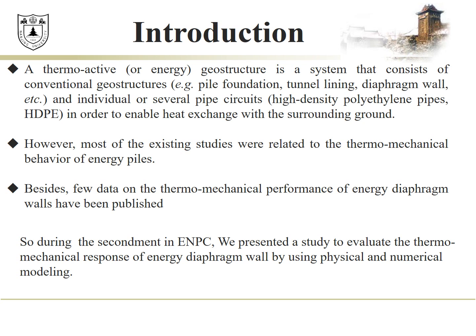However, most of the existing studies were related to the thermo-mechanical behavior of energy piles. Besides, few field data on the thermo-mechanical performance of energy diaphragm walls have been published. So, during the segment in EMPC, we presented a study to evaluate the thermo-mechanical response of an energy diaphragm wall by using physical and numerical modeling.